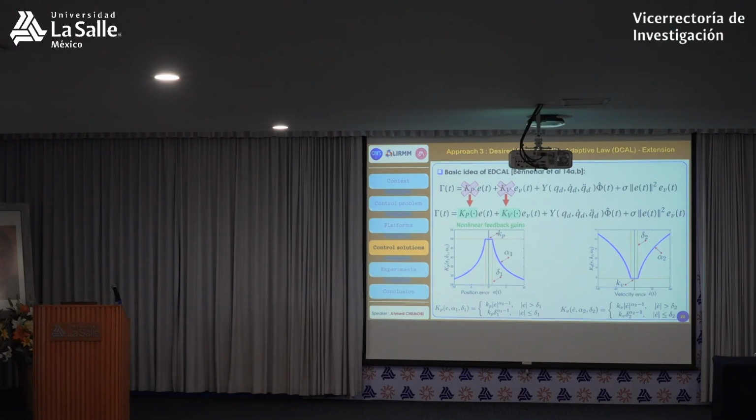Now the question is, okay, we replaced fixed gains by time-varying gains, but what about the tuning? Because with a PD, the previous case with constant gains, you have two gains to tune, Kp and Kv. Now, with the new proposed structure, how many gains do you have to tune? You will have 6 gains to tune. I explain why. Look here, for this first gain Kp, you have to tune alpha 1.